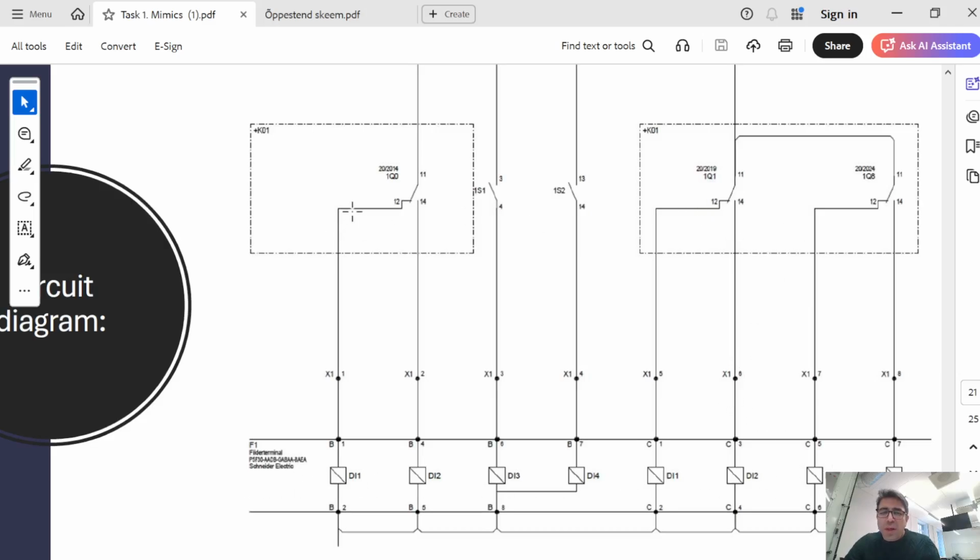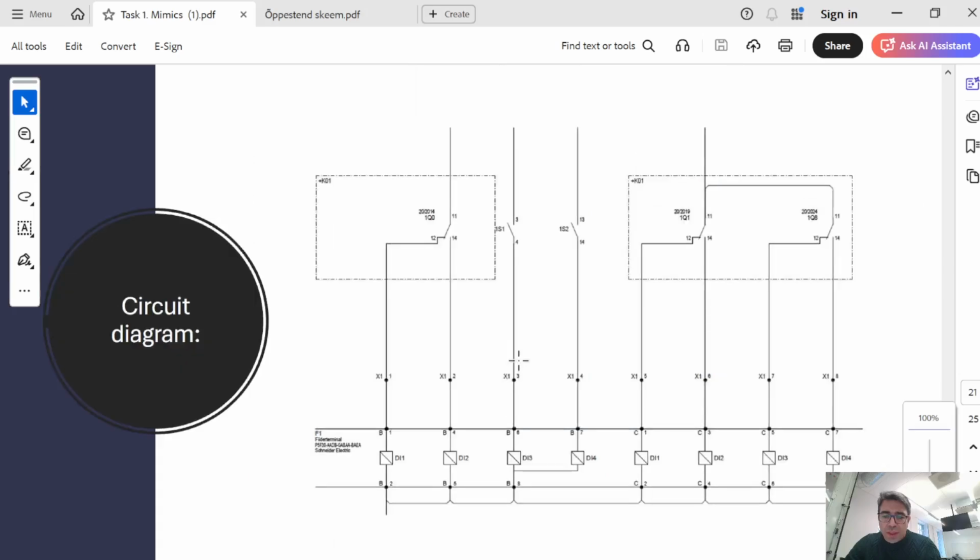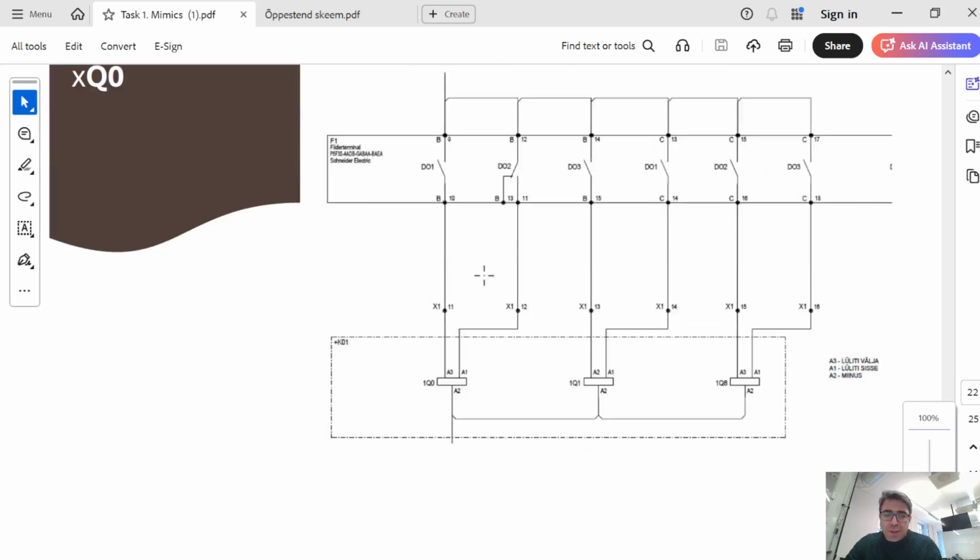You can see how the contactor connections are connected to our relays. So with the push buttons, we have to control the contactors, and the contactors are gonna send signal to the relay inputs, and then relay using these outputs will set and reset these LEDs, the signal lights.